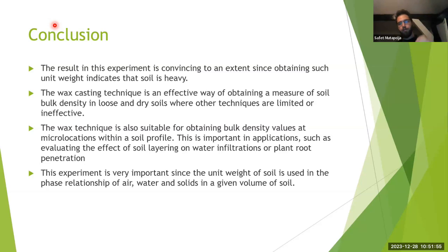The optimum water content ratio is 12%, and you know that you have 7, for example, because you have dry soil. What you're going to do, on the field, I'm speaking about a construction site, is add more water to the soil. You calculate how much water you need for some volume of soil, and you get your optimal water content ratio, for example 12.